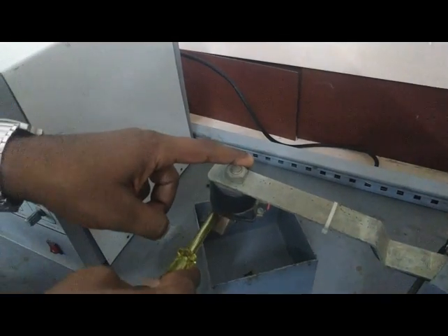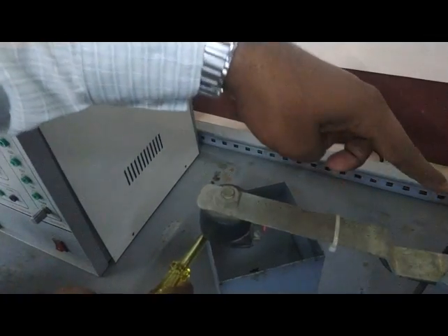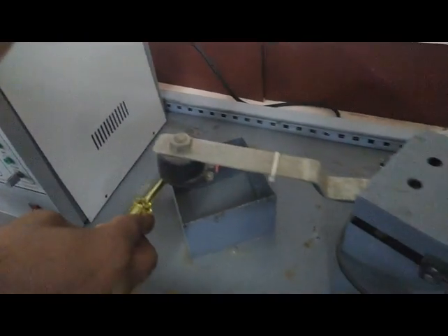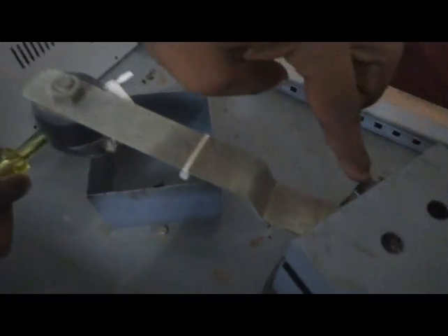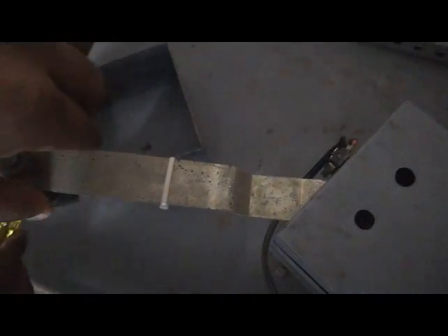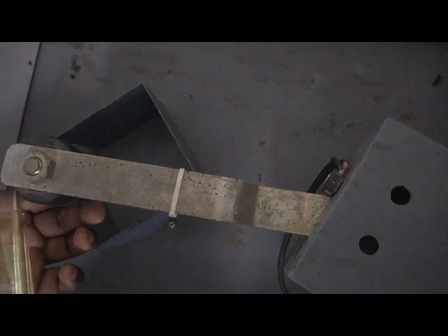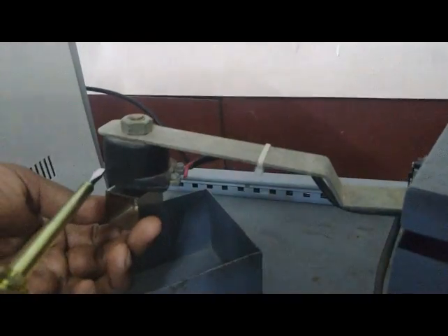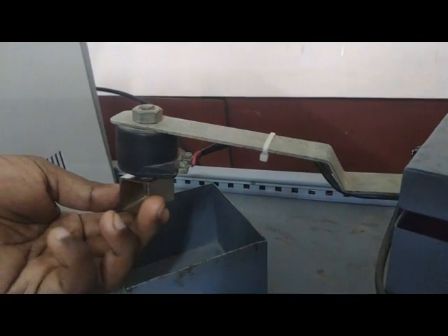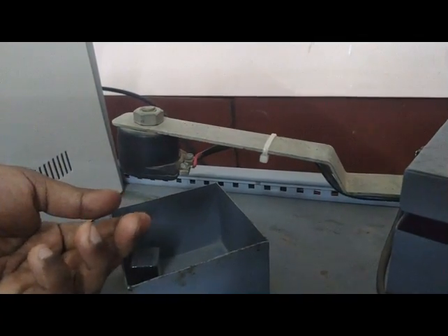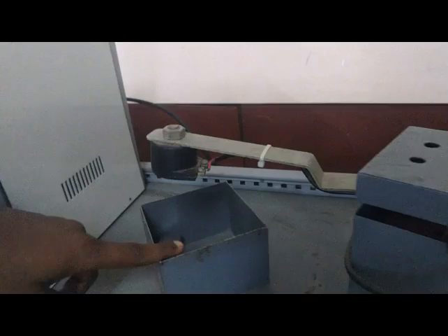That we are controlling through another switch, when limit switch 2 is enabled. This is the other switch. When the arm reaches the position, that will go high, and immediately that should interlock my end effector. So here this will interlock the end effector. This will go low, so that will drop your material to the point where you need to place it.